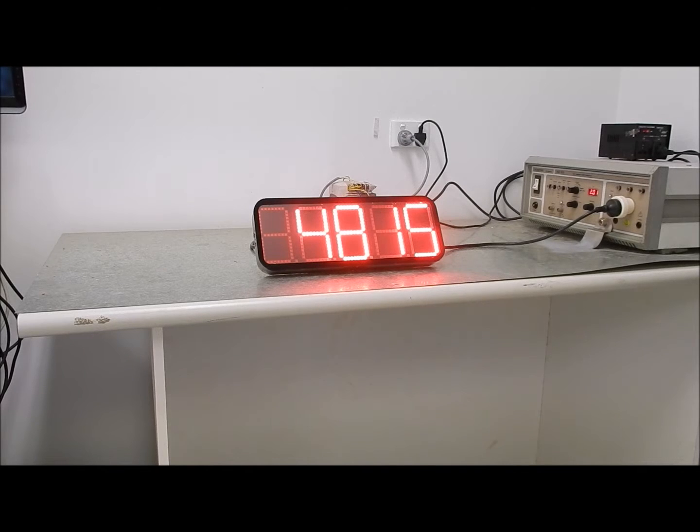So we were doing some testing yesterday on our EMC test bench, generating some spikes and feeding them into the equipment. And I thought it'd be great to shoot some video of what you see when we know we're generating spikes, so that if you see it on the crane, then you know that there's an electrical noise problem. Hopefully then it saves you having to work blind.